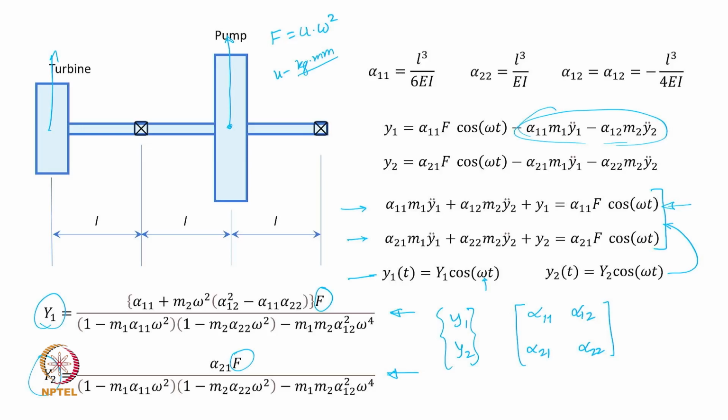Then you will have to figure out which stages have larger mass. Some of the discs which are smaller in terms of mass or weight can be ignored for the sake of getting a first cut idea or guess of the natural frequency of the system. That is how you do it for lateral vibration problems.